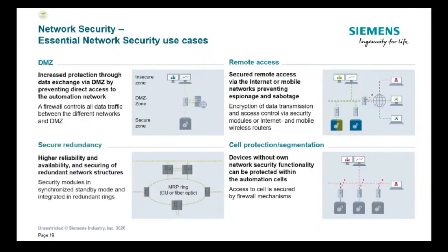And then secure redundancy. I know that we talk a lot about redundancy and the safety measures, but redundancy in a network is also considered part of your overall cybersecurity portfolio and planning. Because if one of the machines in your cells gets an unidentified person in there, typically one of the first and foremost things that a policy calls out is to power down your uplink connection. And if you don't have redundancy, you power down one connection and you lose your entire plant instead of just that one location. So by putting out redundant measures, you allow yourself to take down a segment of your plant while protecting the other segments, keeping those up and running. So having a redundant architecture in place is a cybersecurity recommendation.